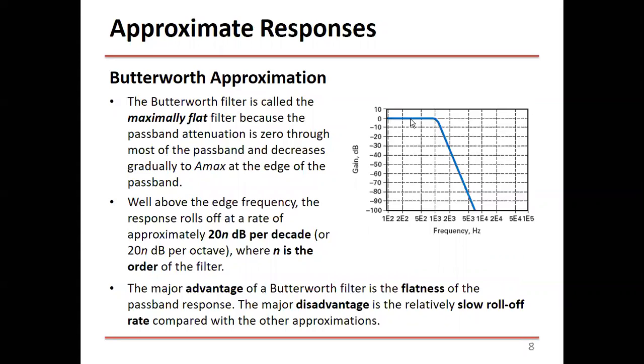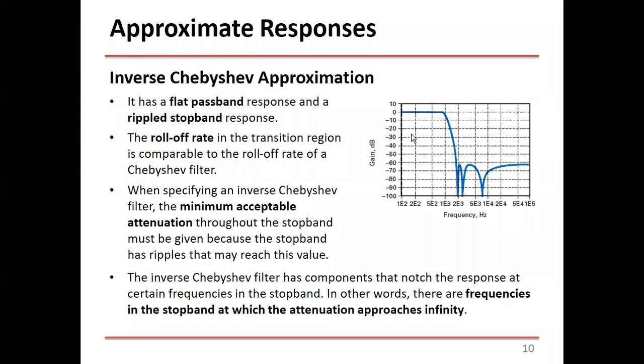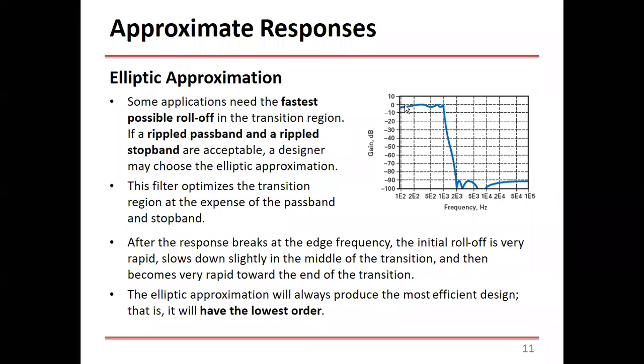You don't see the rolling off of the passband, but it actually goes down. Okay, but it's much flatter than these ones. So you cannot build one with a flat passband and a zero stopband and a sharp transition. This is impossible to be implemented.